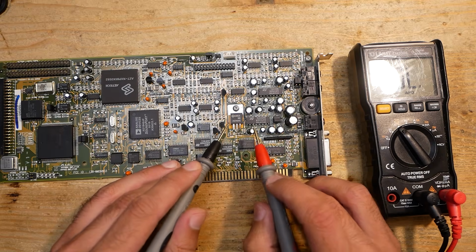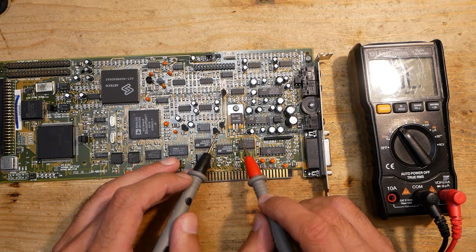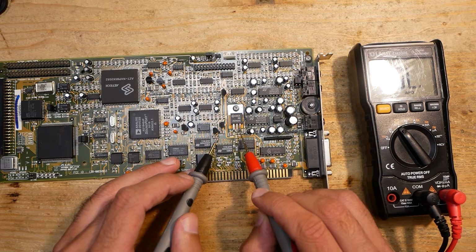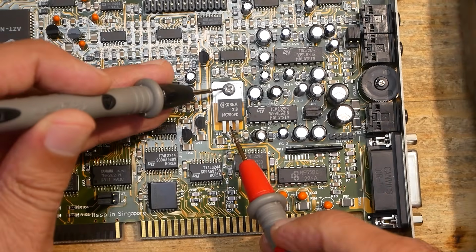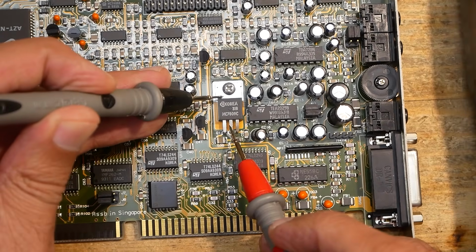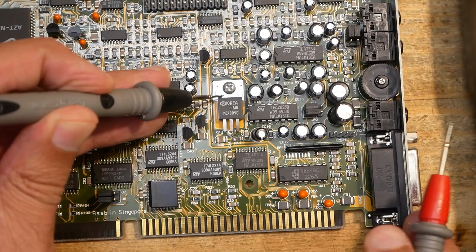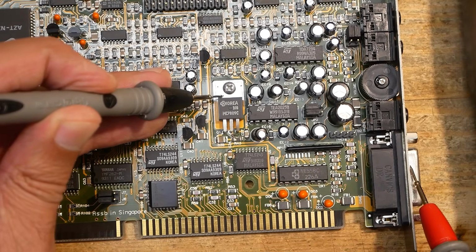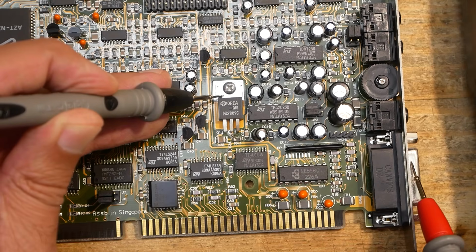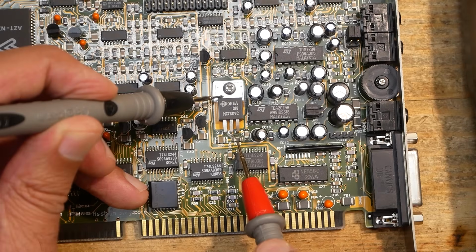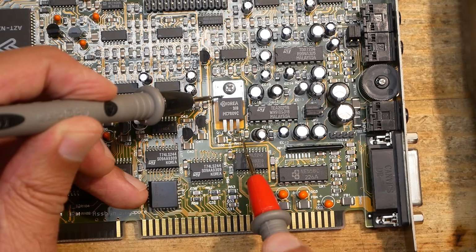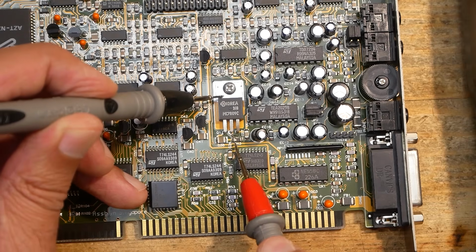Here I can see a burn mark on a resistor which is connected to the middle pin of the voltage regulator. The middle pin of the regulator should be connected to the heat spreader, and it is. It also should be connected to the ground. And here we have no connection. Okay, that would mean that the regulator doesn't get the ground, and so it can't regulate the voltage properly. What would probably end up in a non-working amplifier and a silent output.